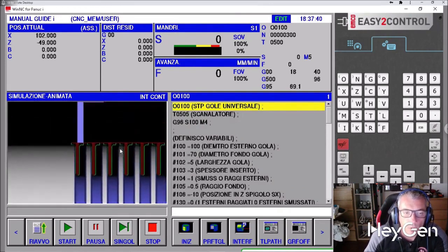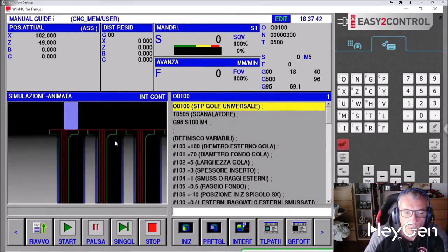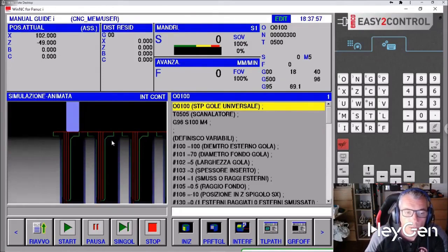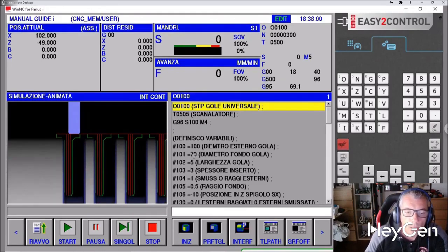Because, for example, I've already thought about not reaching exactly parameter 100, but going to parameter 100 plus a couple of tenths, and reach it here at parameter 100 with a bevel to avoid leaving shadows, but I'll let you do some of it too. Otherwise you can simply reduce the bottom diameter a bit, increase the bevel, and then physically start from 100.2. There are 1,000 ways to avoid shadows on the pieces, but it's a nice starting point.